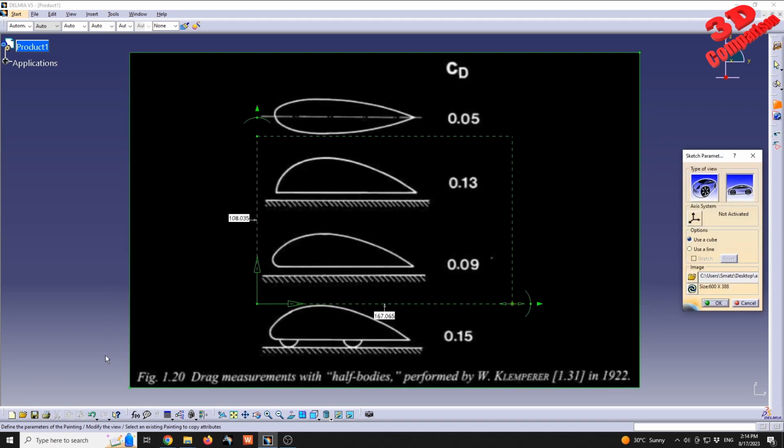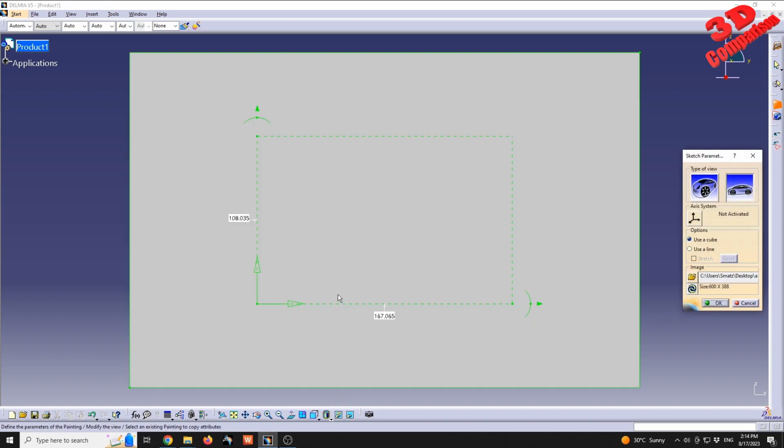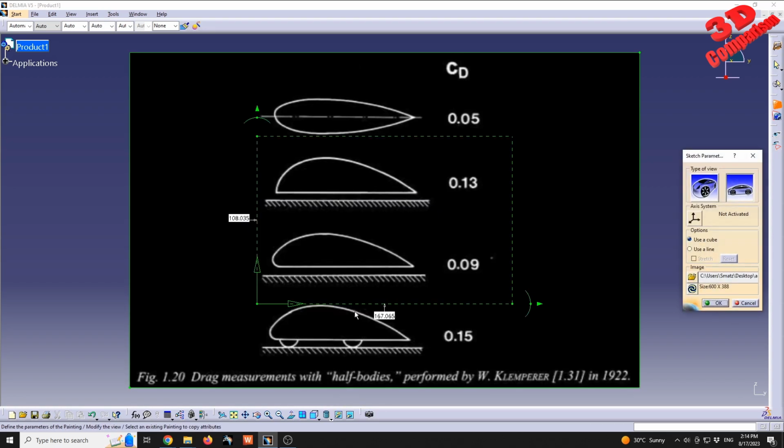We're gonna be prompted with the image loaded. If for some reason you worked maybe in Part Design previously, you will also have a warning over here to swap the shading. So this workflow requires shading with material in order to have that image displayed. Maybe by default you are in shading with edges, as if you model something in Part Design, you don't need texture over there. So keep that in mind. You can swap the viewport at the bottom to shading with material.